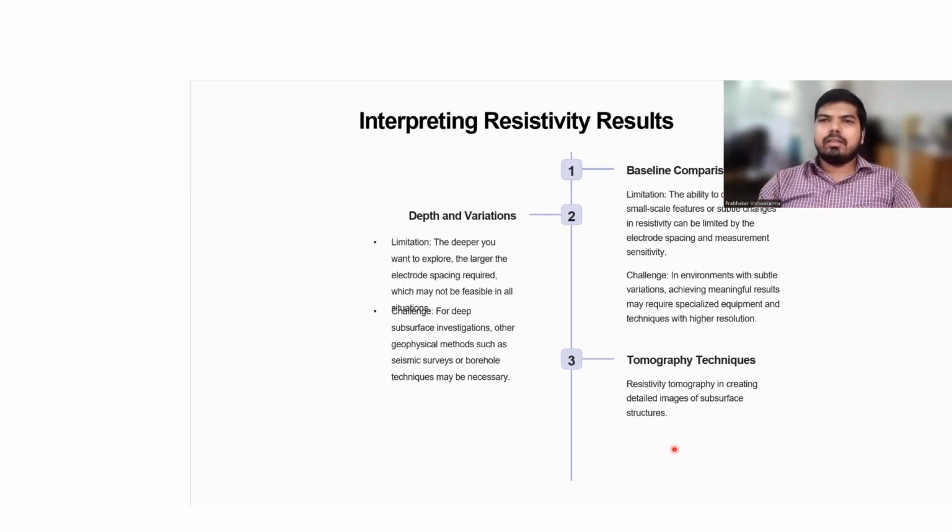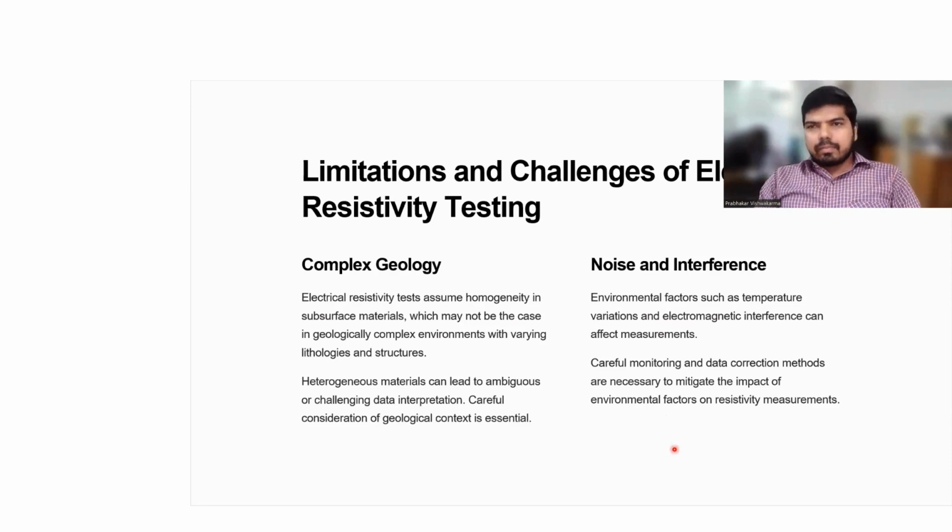Now, the challenge in the electrical resistivity test is complex geology. The electrical resistivity test assumes homogeneity in the subsurface material, which may not be the case in a geologically complex environment with varying lithology and structure. Heterogeneous materials can lead to ambiguous or challenging data interpretation.